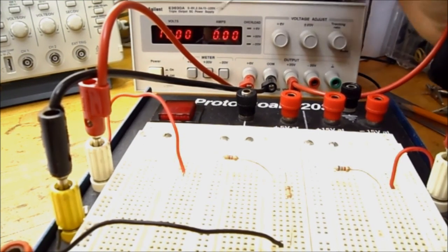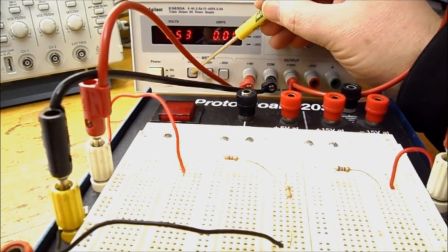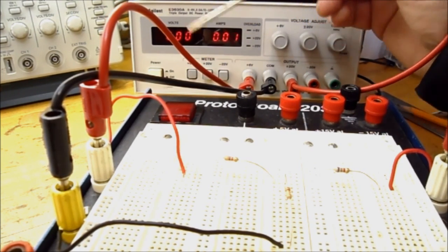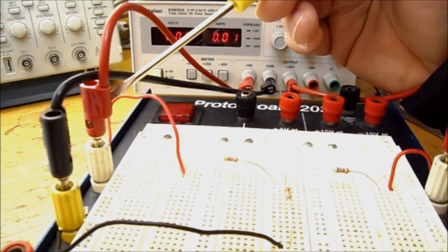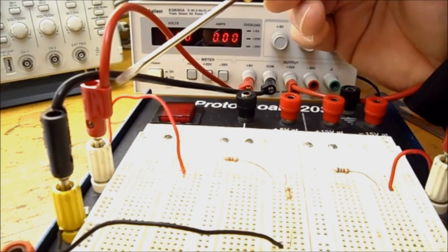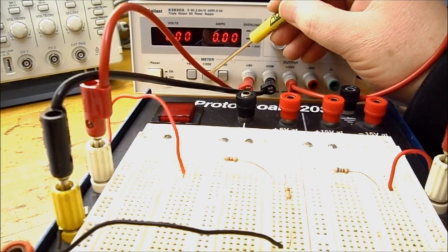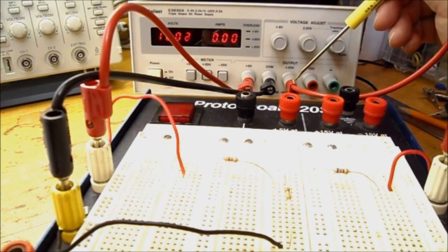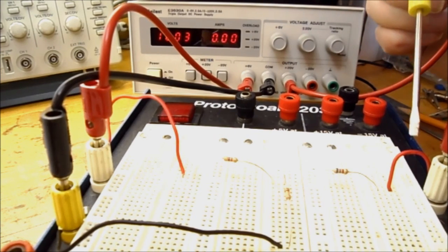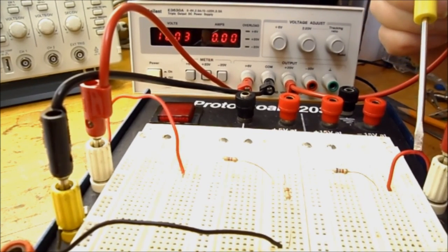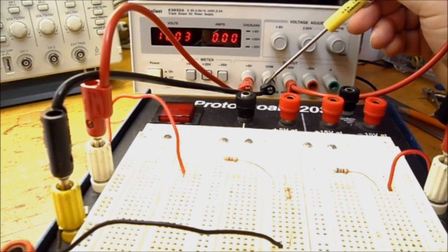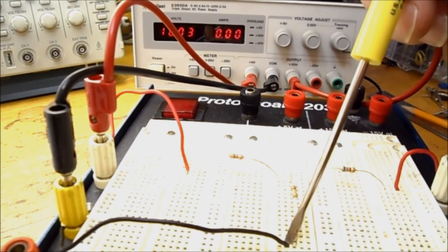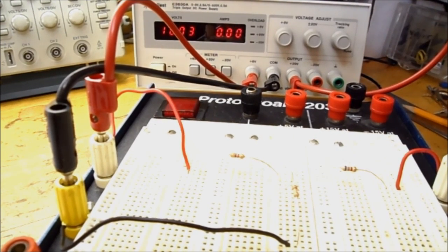So looking a little further back, you can see if I press the +6 on the meter, I have 6 volts coming in from the +6 terminal to this side of my circuit, so that is E1. If I press the +20 volt meter button in, I have 10 volts, and it's coming out of the +20 volt terminal to this side of my circuit, so it is E2, and the common is coming to the bottom of R3. So that's the circuit set up as it needs to be.